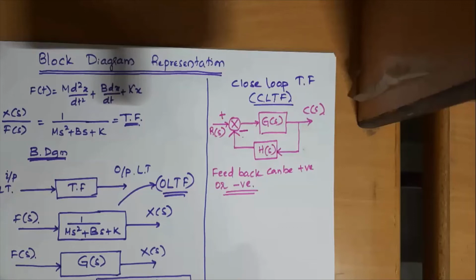Then eventually it fills up and suppose it goes to 11 meter height. So the error signal is 10 minus 11, that is minus 1. Minus 1 actuating signal, in the sense you can interpret it like you are generating an actuating signal to operate the motor in the reverse direction. I mean, it should take out some water. So the same kind of feedback will take care of both.